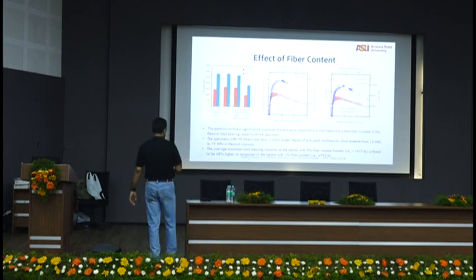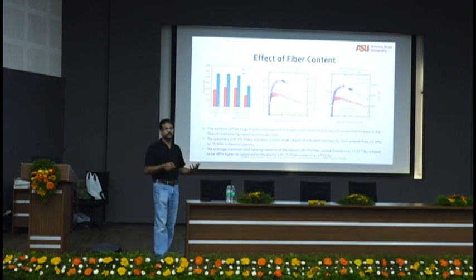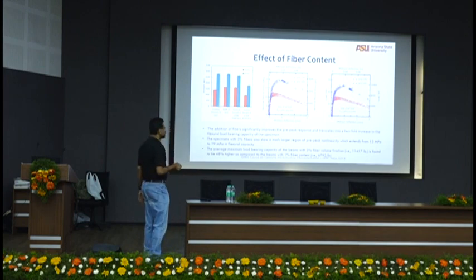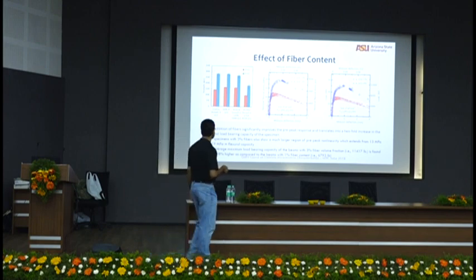So effective fiber content: you can see here cracking strength with 1% and 3% fiber volume up to 3000 psi, that's about 20 megapascal. So cracking strength or flexural strength of 20 megapascal. Okay, so M20 in flexural strength, not compression. Typically your flexure is what? 1/8 to 1/10 of your compression. So you see at 20 megapascal flexure with 1% fibers, with 3% fibers, it's even higher.